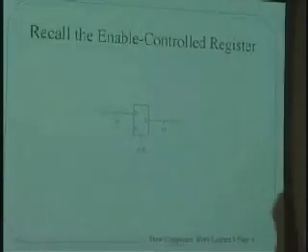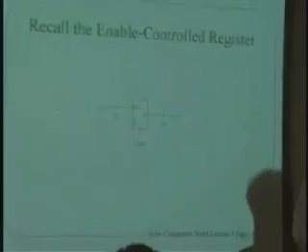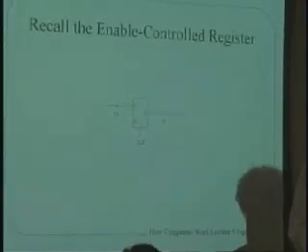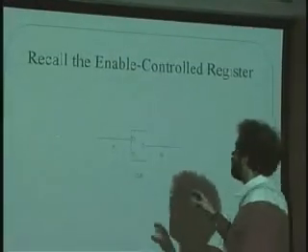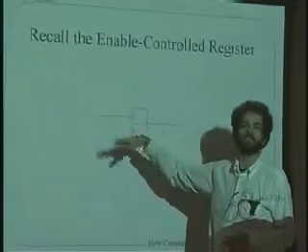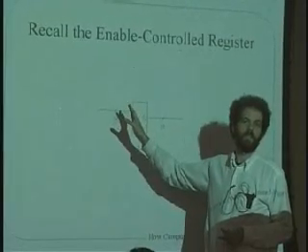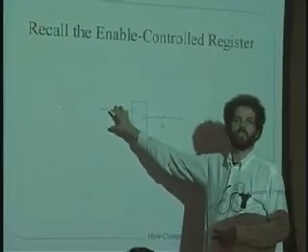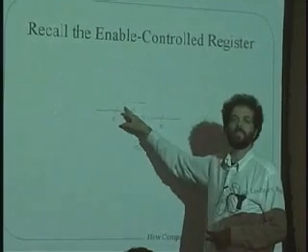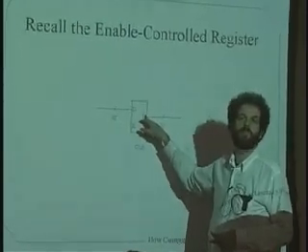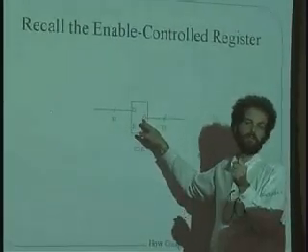So what value does D have then, when Q takes on the value of D? Well, after the snapshot is taken, what's in front of the lens can change however you want. So we don't specify what D is, except that when the clock goes off, whatever D is, Q takes a hold of that and latches onto it for some time.